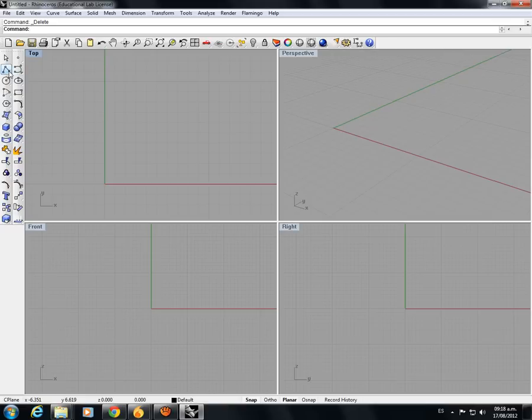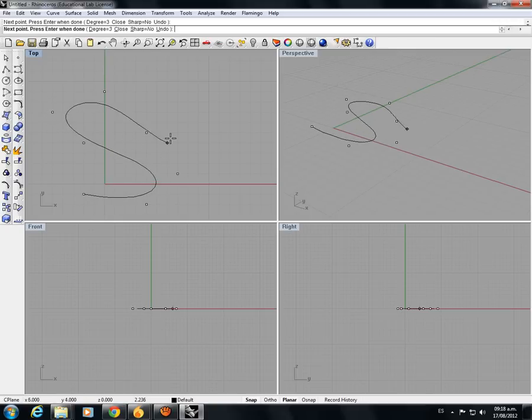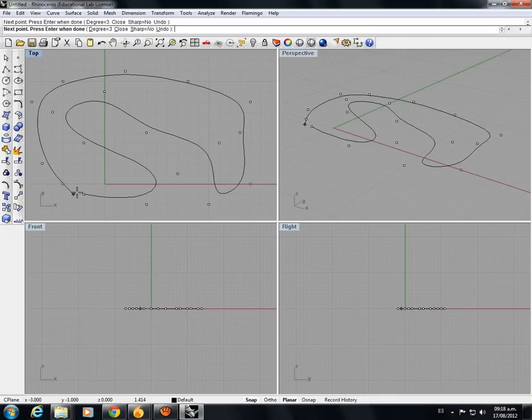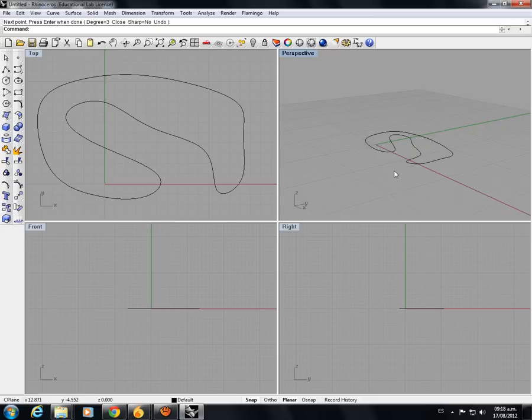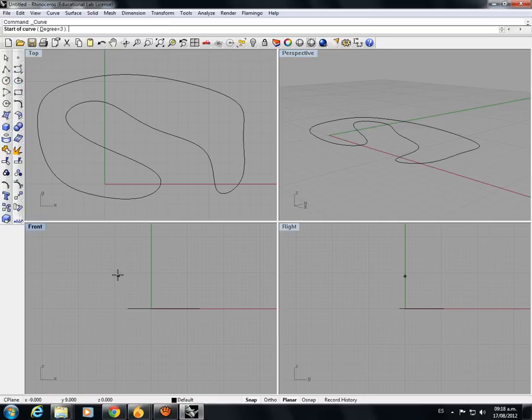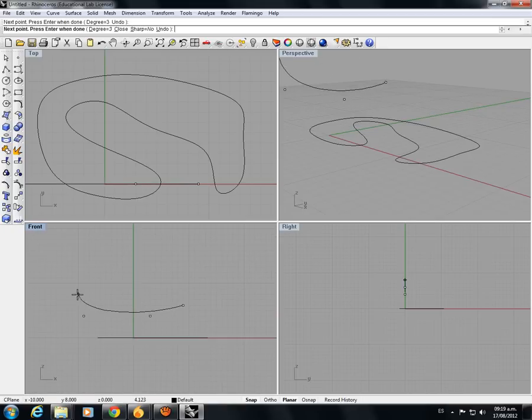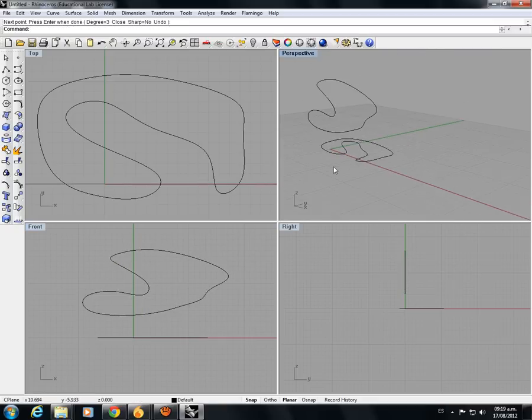Now on the right of this option, you can see the control point curve. Now if we click on it, we can make curves on the top view, and they will be drawn, of course, on the floor. See? So you have a curve that you drew on the floor. Now what happens if I want to draw another curve but on the XZ plane? On the XZ plane, I can draw on the front view and I'll be making a curve.